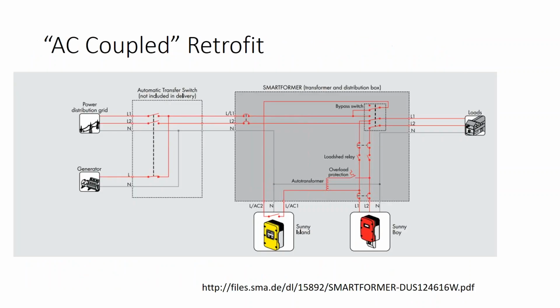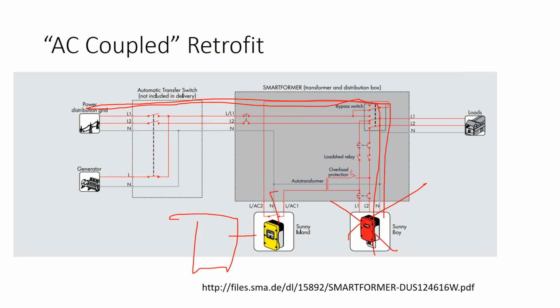And regular solar arrays, because they are hardwired into the grid, have to shut off when there's a power outage. And so imagine how dumb you must feel in New Jersey to have a $30,000 or $40,000 solar array on your rooftop and you don't have electricity. You should be the emergency hero of the community, and now you're the laughing stock of the community. And all you need to do in that case is to get a battery inverter and a battery and AC couple it.